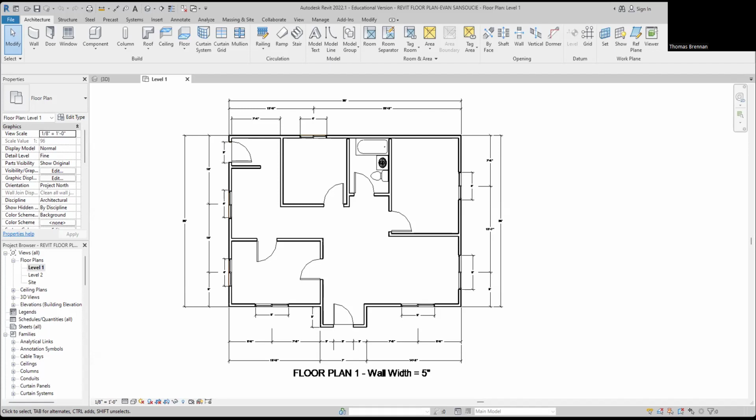All right, go ahead and give that a shot. Make sure that makes sense. So you're always going to align it. In this particular case, since it tells us it's 8 feet, we just want to verify we got the hang of this. So you want to make sure that it's going 8 feet right on top of it. That's the right foot dimension right there. Just go ahead and try it one at a time, guys. Make sure you got that. Then we'll try one of the ones that's got some inches on it. Does that make sense? This one is a little bit different because you've got fractions and so forth as you're working with the architect scale, but it's the same idea. Just got to count it.